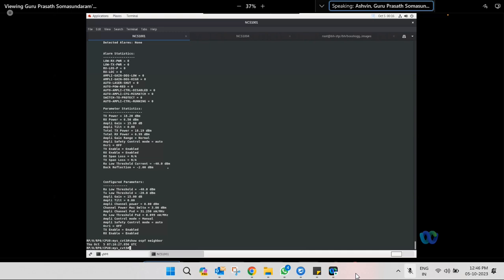Is the expected trace there for the other end also? What I mean is that on the other end also, it is not forced that you have to connect only slot one to slot one, because it is all light. If you connect slot one to slot three, as long as it is receiving power, it will continue to work. You cannot tell that it is connected wrongly, because at the end both of them are amplifiers. So you will not raise any alarm in that case.